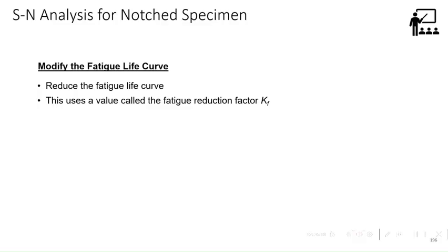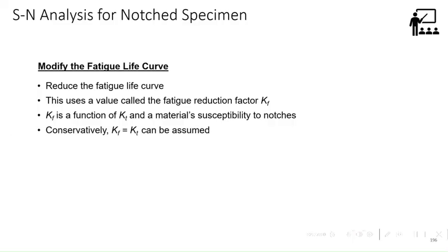material. And for aluminum, that is 75 to 80% at 10³, and there is no endurance limit. Fatigue strength at 5 into 10⁸, you should take 40%. That we already saw in the last class. So you can again generate an SN curve for the required KT value based on the related material properties. To start with, you can take KF, but you can calculate KF. This is one way of doing approximation, but we can calculate the KF.